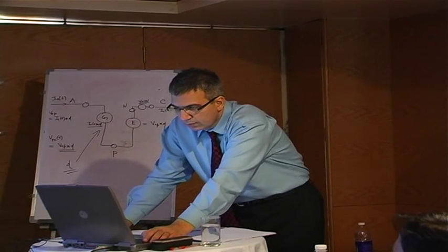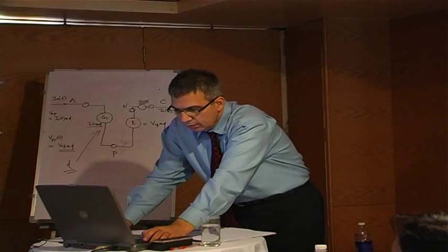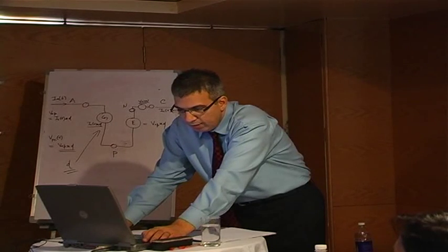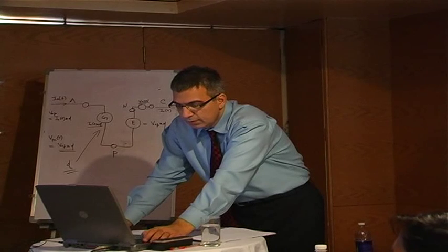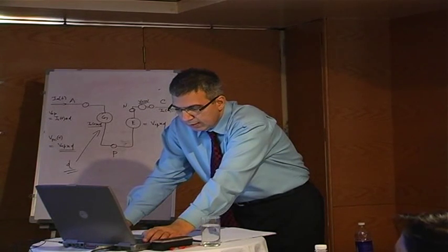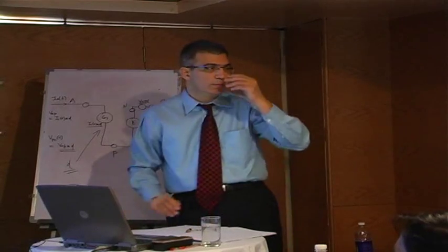So this, and it basically goes to 0. Inductor current will be rising. Steady state voltage across the inductor is 0. You have a voltage swing here, which goes from 6 to -4, but eventually when you reach steady state, it goes to 0. Okay, and let's see here. So this is the buck. Any other questions on this one?